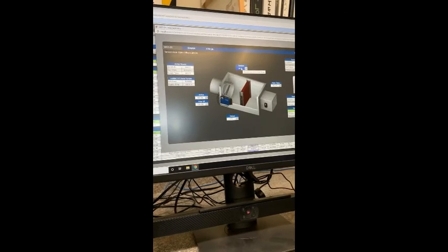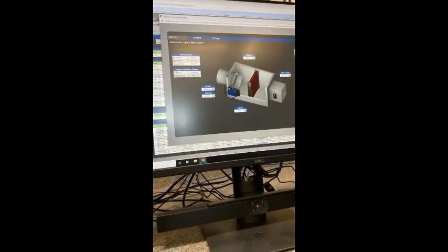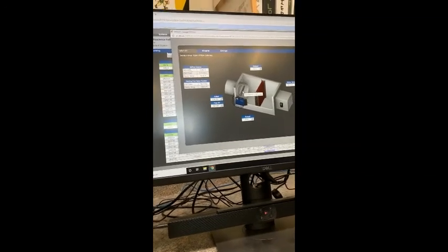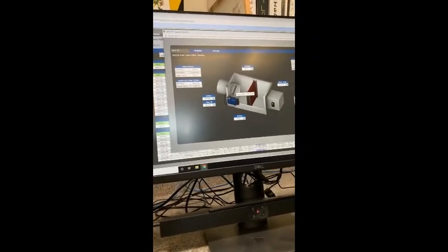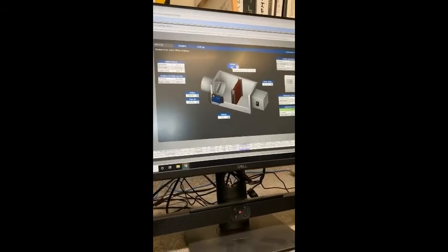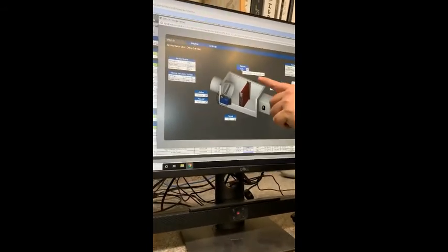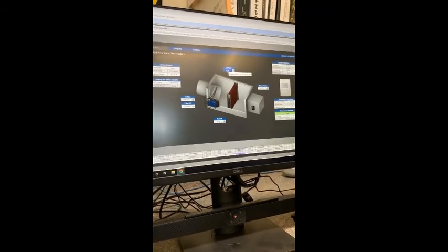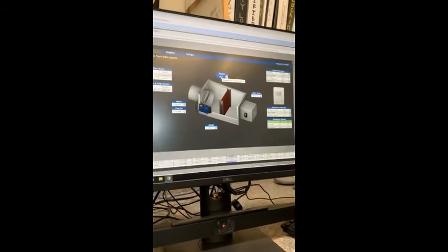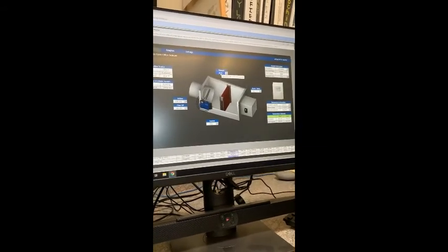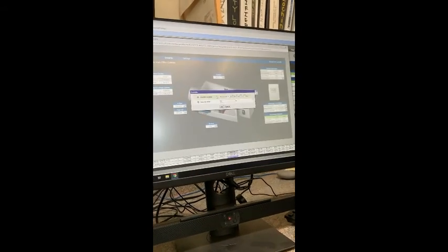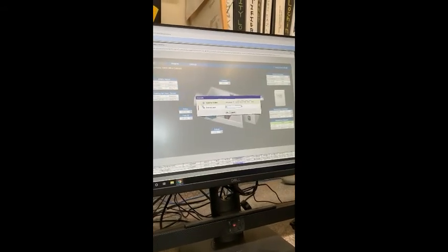So these are based off of the damper. There is a damper command and a damper position. This is the damper command point. When we put the mouse over it, it'll show you a point name, and it'll give you a little bit more information. It'll tell you what the value is, and that default means it's not being overridden, basically. If I were to go over here and override that to say 30,